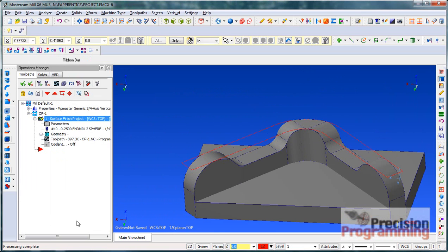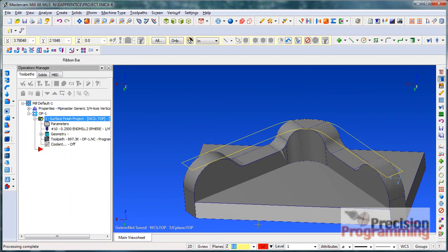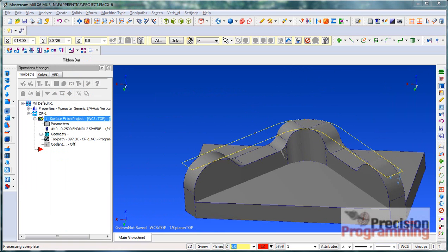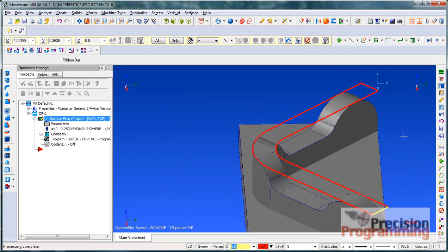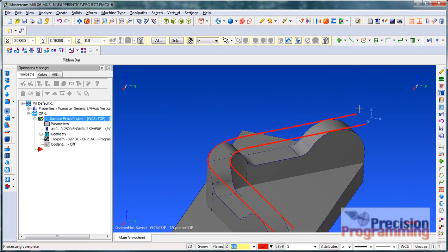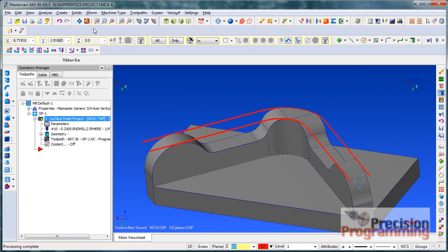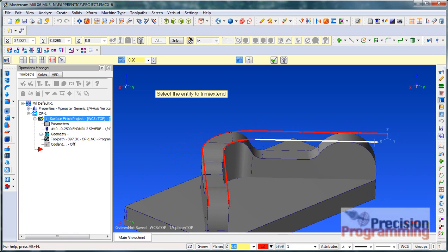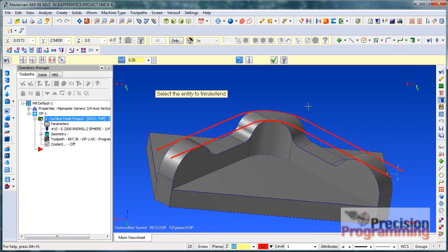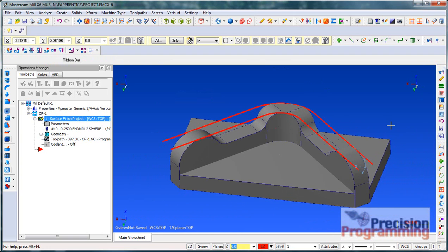Let that get projected above. I'm going to grab this geometry real quickly and make it a little bit thicker for visual. I'm going to go ahead and remove this because it doesn't have to be a closed containment, and actually it does not want to be a closed contained area. I'm going to extend the end so I can get the tool to go a little farther out, because it still uses the center of the tool to the center line of the geometry. So using that thought of adding an extension of maybe .260 using a .250 ball end mill, I've got what I need there.